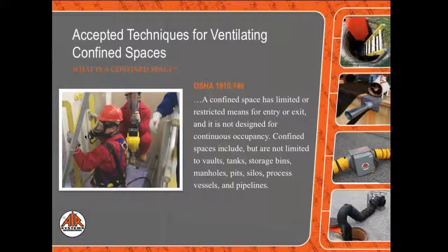It is important to be able to identify confined spaces because they need to be ventilated properly to ensure worker safety within that space. For additional information, consult the Occupational Safety and Health Administration's 1910-146 document.